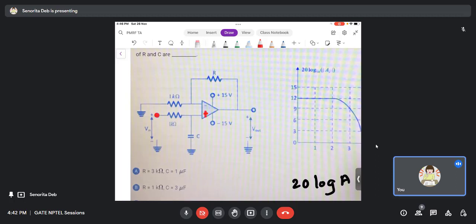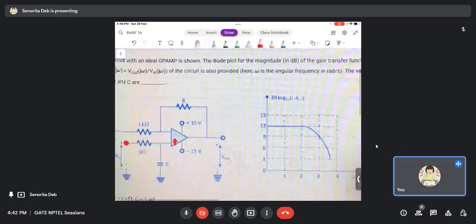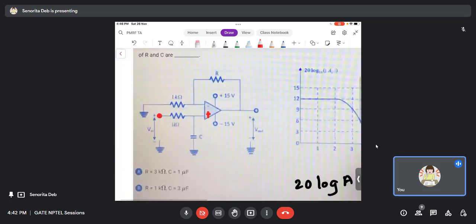Right? So if you solve, now what will you start doing? That okay, there is an R and there is a C and I will have to apply KCL across the cap also. No, you need not do anything. Why? So at DC what will happen? The gain which comes is basically the DC gain we talk about, right?